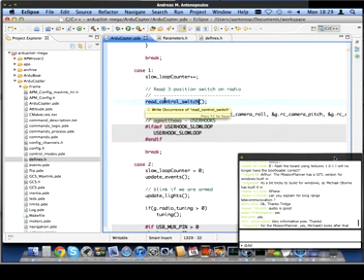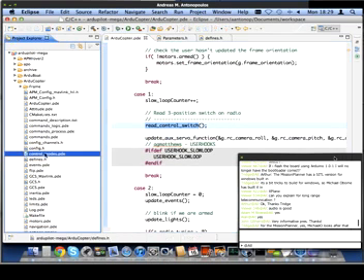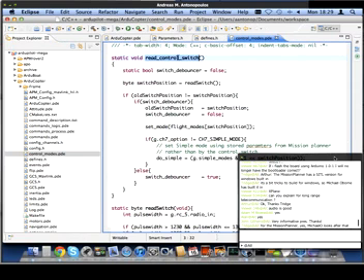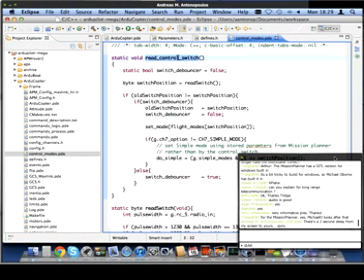Actually, I think Tridge showed you this earlier. This is being read in the slow loop at 3.5 hertz, and that function's purpose in life is to look at the current switch position and update the control mode variable. You can see where that read control switch function is implemented in control_modes.pde right at the top. Andres, can you go to control_modes.pde? Yeah, right at the top. So right there, that's where it's implemented.